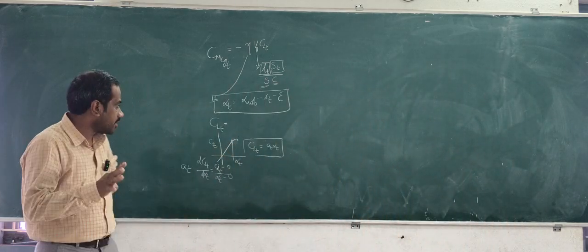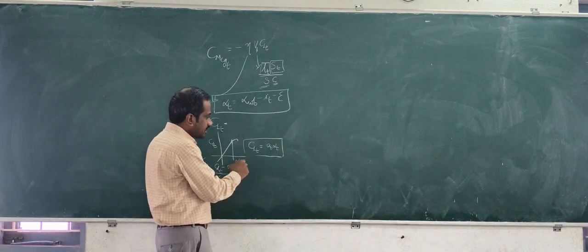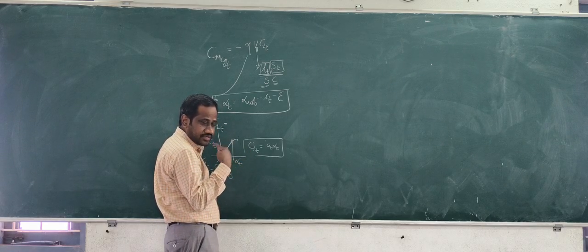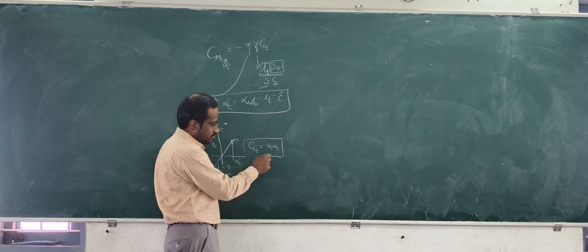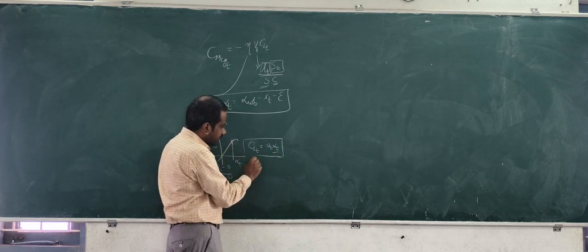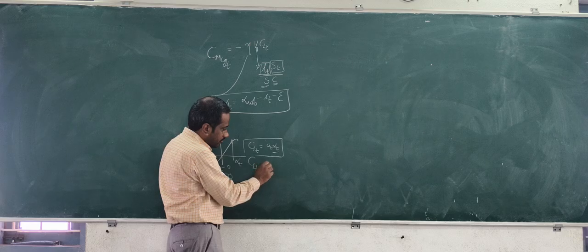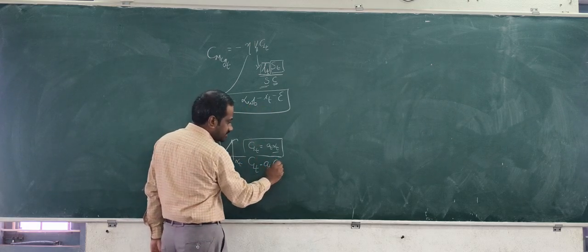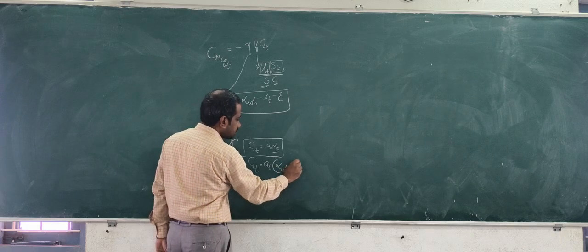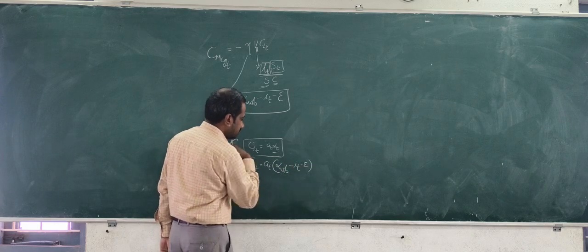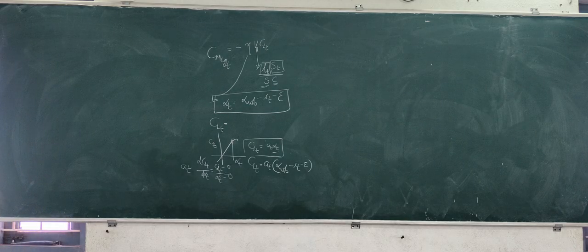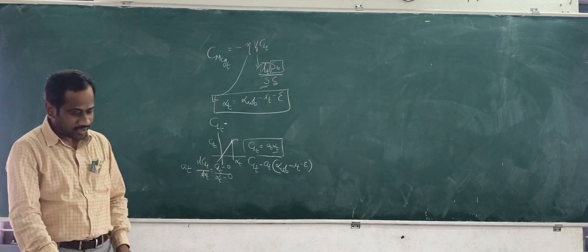So this is one incorporation I would like to do. So CLT. What is CLT? Coefficient of lift of tail at one particular angle of attack is written. So what is alpha t? Look at what all we are trying to do. AT into alpha t contains these many things. Alpha WB minus IT minus epsilon. So CLT is elaborated. Coefficient of lift of tail is elaborated.